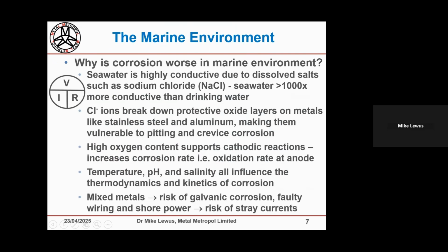And I've answered, why is corrosion worse in a marine environment? Well, I've partly answered the question. The fact there's so many ions in it allowing current to flow in seawater means the resistance of seawater is low, the conductivity is high. So you probably remember this. It's like the schoolboy physics mnemonic on what sort of current we expect if we've got a certain voltage or resistance. Well, if we've got a low resistance for a particular voltage, we're going to have a high current